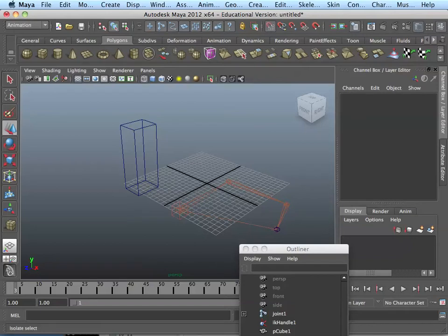Speedpaper, right? You poke a hole in it, you put a mark on the servo, you set it to 0. You mark it on here. You set it to 180, you mark it there, and you measure on here how many degrees you've gone. Really simple, but I did a whole project without this one time. It drives you crazy because you sit there with a protractor and everything else, like, all right, how many degrees have I gone? And then one day I thought about it and just made it out of matboard the first time.